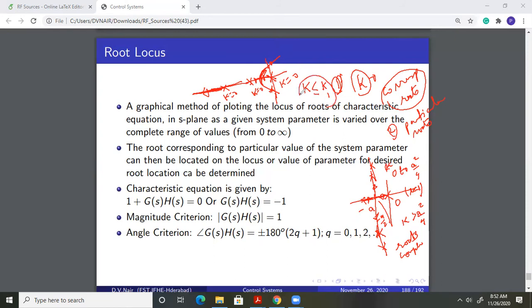So we will see how to find this out, something interesting. But you see, this is what I mean when we say that the root locus allows us to find out the value of gain k for particular roots. So we can find out what the gain k is when roots are imaginary, and as long as we keep this gain k less than the value for which roots become imaginary, the system remains stable, and any increase in k greater than this would lead the system to be unstable. So we will see these two points.